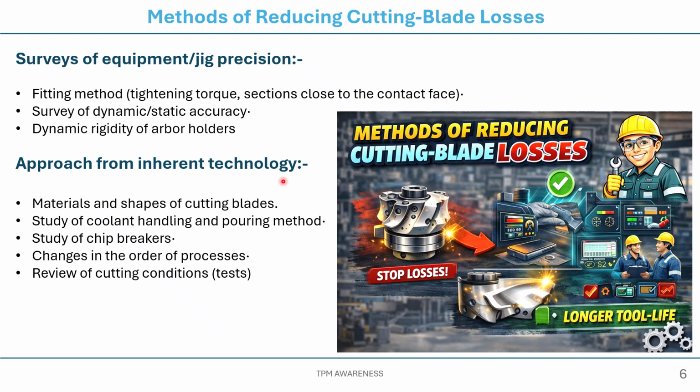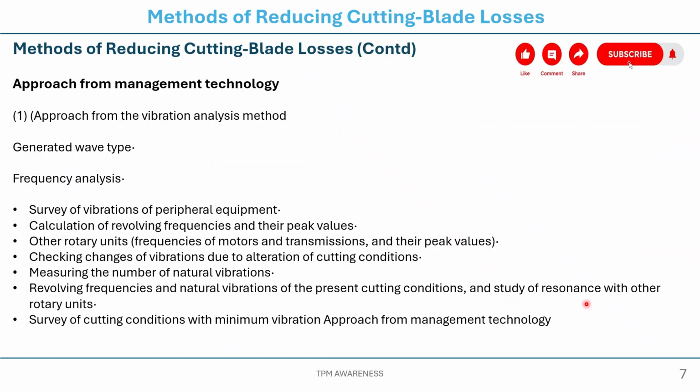Approach from inherent technology, that is material and shapes of cutting blades, study of coolant handling and pouring method, study of chip breakers and change in the order of process and review of cutting conditions. So if you reduce this, then the life of your tool will be longer.